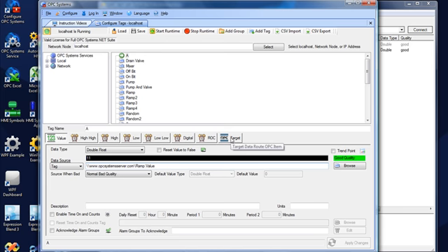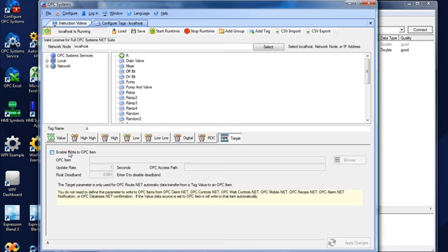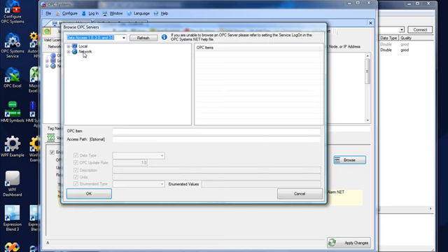Now we'll move over to the Target tab, and this is where we're going to enable an automatic write to another OPC server. So we only need this feature for automatic transfer from one OPC server to another, or maybe we're using a calculation as a data source to network multiple items together into one common value and then send the result back to an OPC server. Now here we're always going to select a local OPC server. We do support remote DCOM, but for the easiest connection you'll choose the local OPC server.